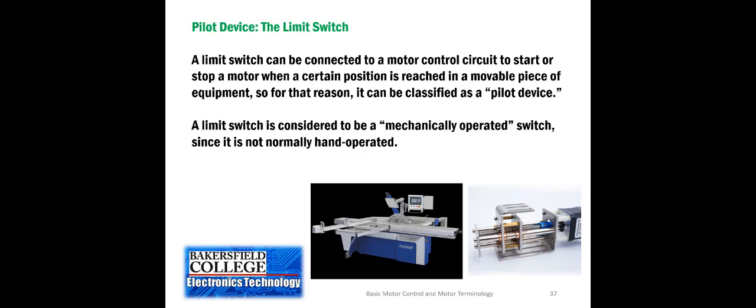And what we can do is put a limit switch at the end of travel on the left and on the right side so that when the motor reaches the limit switch, it's turned off. Otherwise, the motor will want to keep turning, it will be stalled, it will heat up and burn up, or we could be breaking mechanical parts. If that motor is strong enough, it could snap the components of that movable cable.